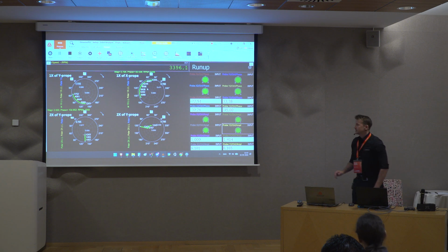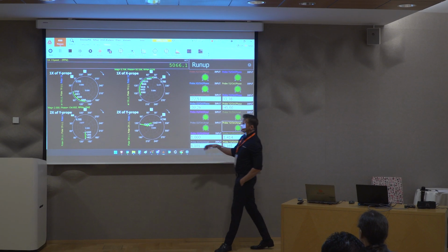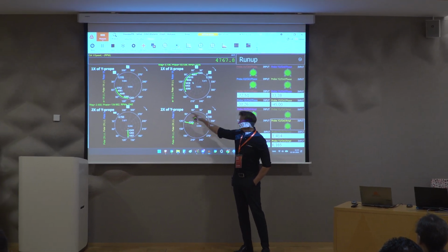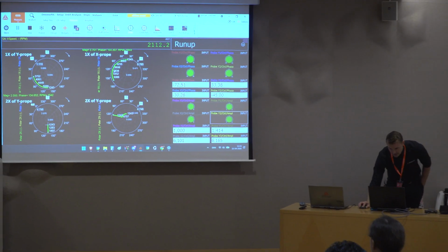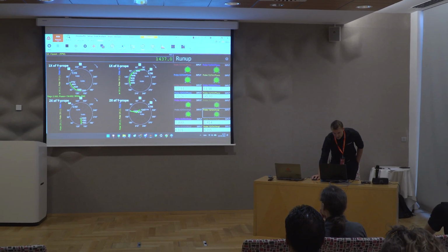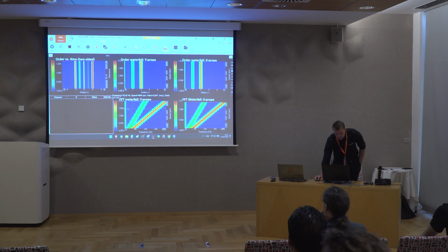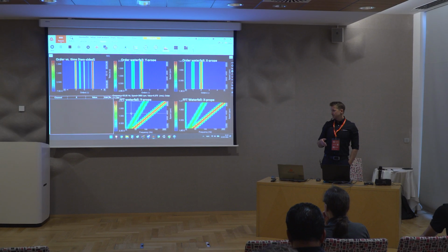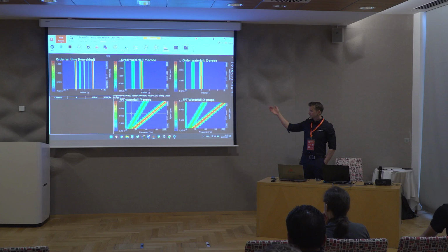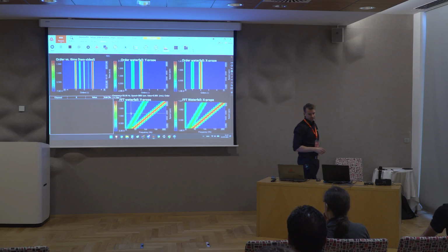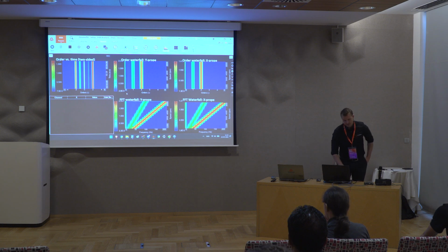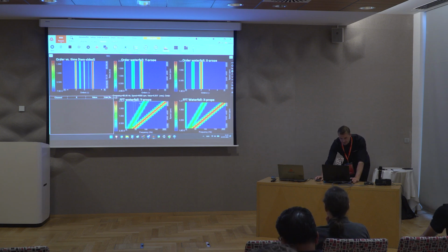So this is actually pretty useful to follow, that you ramp up and suddenly this one starts changing phase and changing amplitude. Then we also have waterfalls, so you can follow in time, both in the frequency domain and in the order domain, what happens across speed and across time. And these are all things that you would like to look at in order to make sure that your machine is running as optimally as it should.